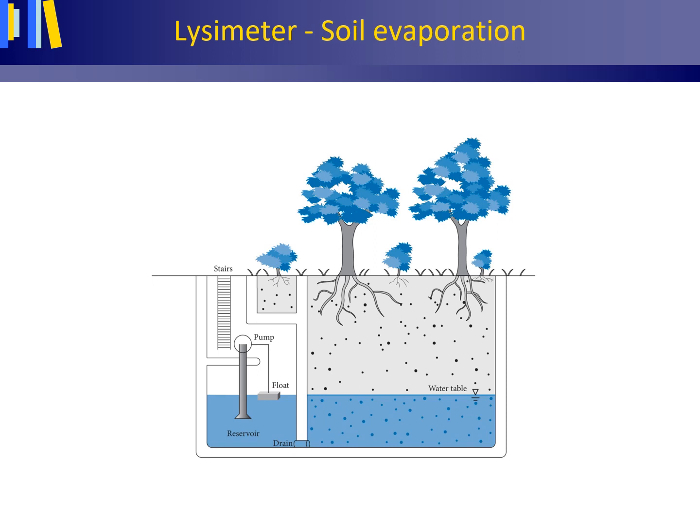The diameter of a lysimeter typically varies from 0.5 to 2 meters, with larger devices having surface areas of the order of 35 times 25 square meters. Lysimeters are difficult and expensive to install, but are most useful in experimental research for obtaining empirical equations to estimate evaporation from meteorological variables. In the Netherlands, 4 lysimeters with a long track record since the late 1930s are located in the dunes nearby the township of Castricum.